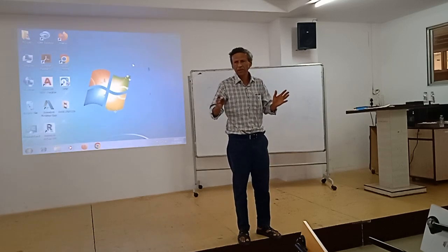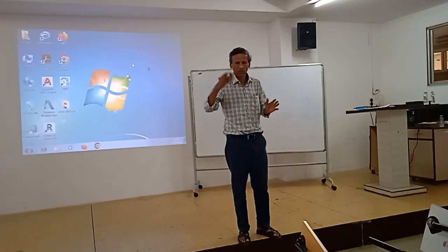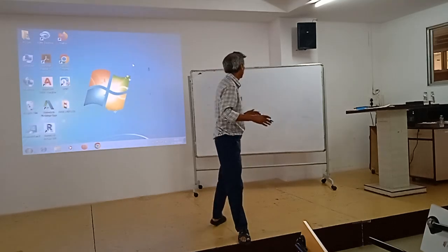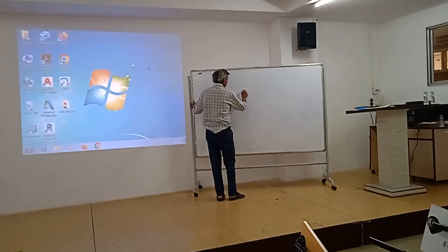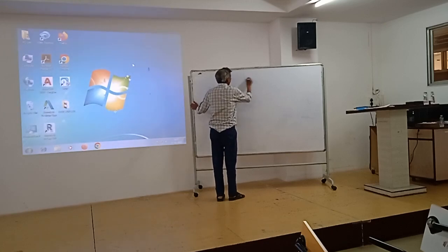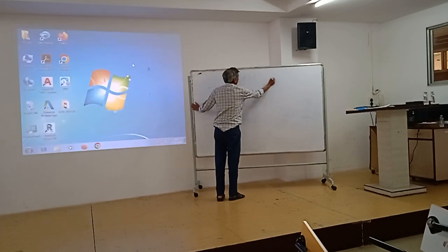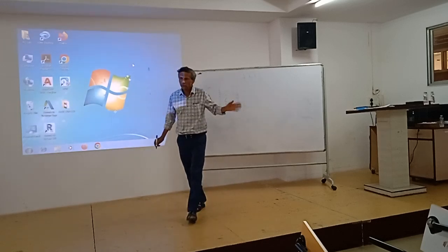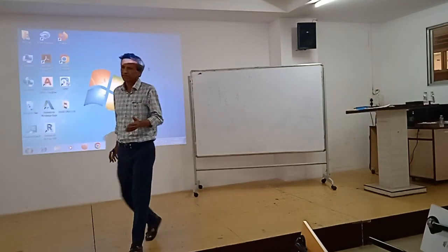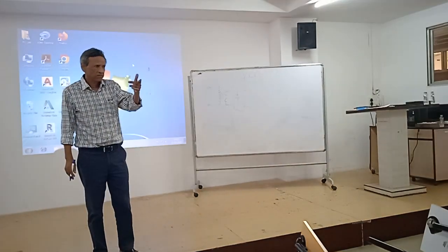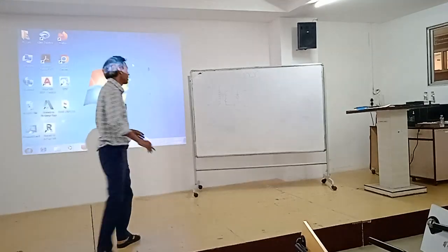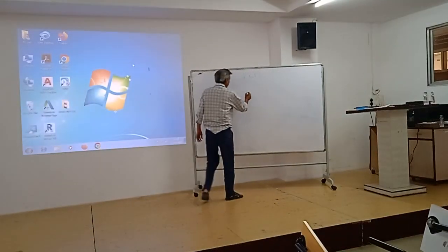These are all simple points, but you can always stop me without hesitation. And then this will have this type of supply, full wave rectified. So what should we put after this? Filter. Filter capacitor. So I am putting a filter capacitor.